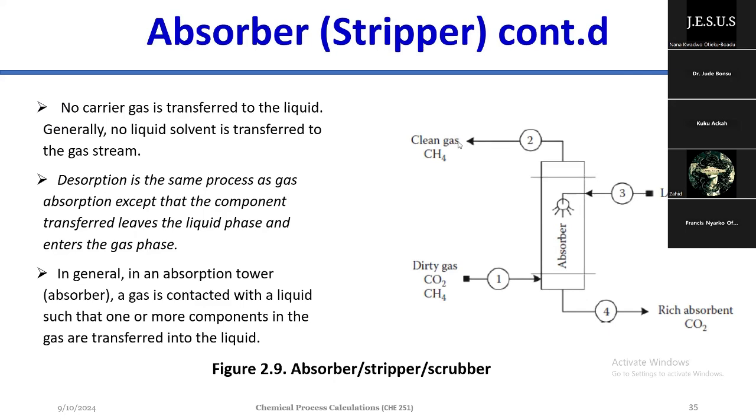So there's something they call a de-entrainer or demister. Some solid thing that is there, which kind of knocks the liquid. So usually the absorbers have something at the top where the gas is leaving, they call it the de-entrainer or the mist eliminator. There's some solid bar which the gas is able to move around, but the liquid kind of hits it and comes back.